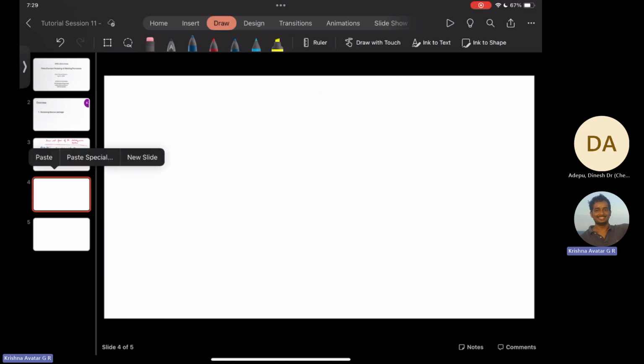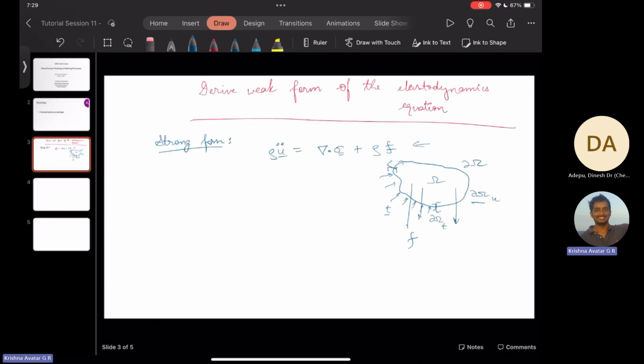So this implies that it's displacement boundary conditions on this area, and on this area we are applying some traction boundary condition. So this is just a generic body. To have this problem as a well-posed problem, we'll have to have, subject to, which are also essentially the boundary conditions, U vector at any point X vector equal to U naught vector, isn't it?